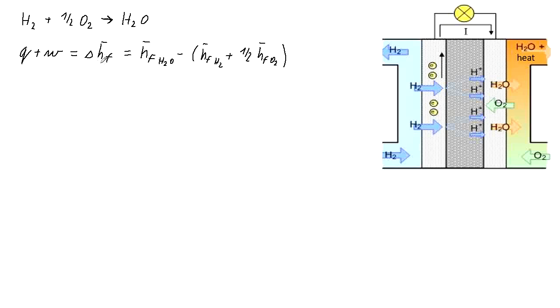So now how to get the enthalpy of formation. There is something called standard enthalpy of formation at reference temperature of 25 degrees C and the reference pressure of standard pressure 101.325 kilopascals, and it's denoted as enthalpy of formation 0. And then we will need to add the enthalpy difference given by the different temperature that we have. So here we have the temperature 100 degrees C.